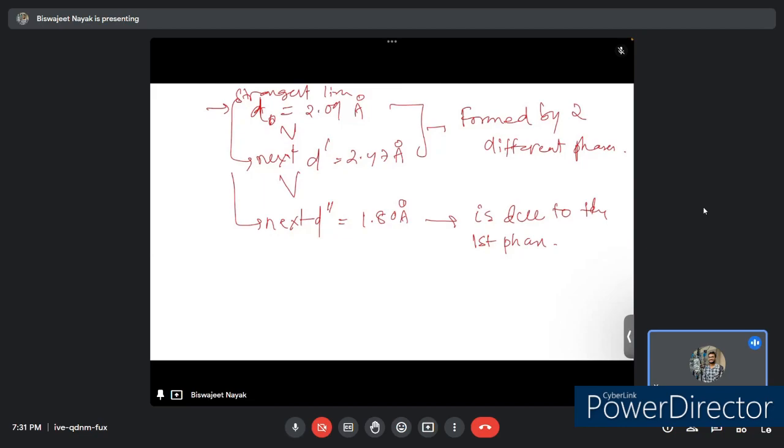So the analysis of a mixture becomes more difficult when a line from one phase is superimposed on a line from another, and when this composite line is one of the three strongest lines in the pattern of the unknown. The usual procedure then leads only to a very tentative identification of one phase, in the sense that the agreement is obtained for some d values but not for all the corresponding intensities. So this in itself is evidence of line superposition.